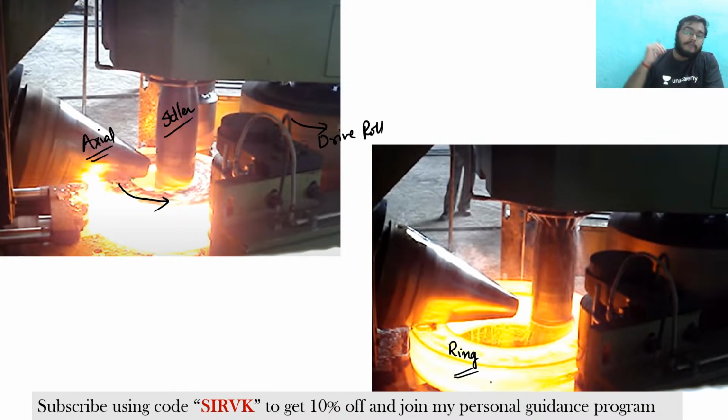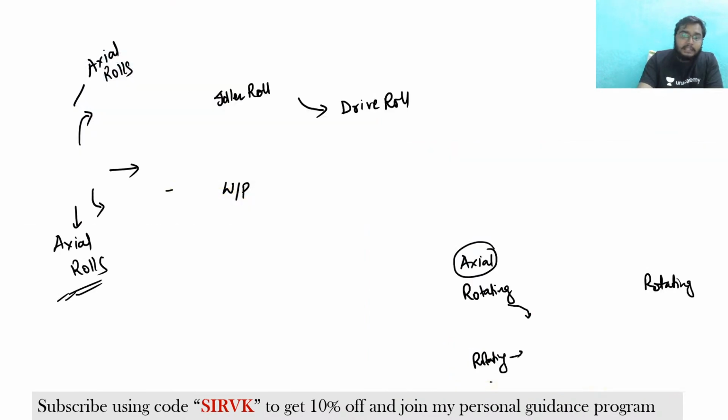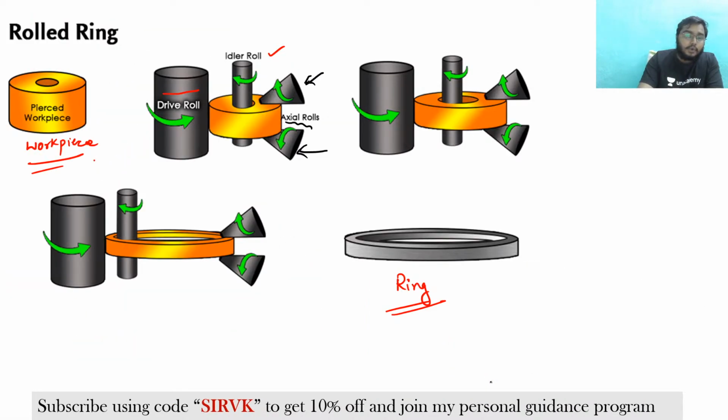So I hope you visualize these things, how in the industries, in the manufacturing unit, rings are produced with the help of rollers, and that's what is being shown in this figure. There is a workpiece, a drive roll, an idler roll, and axial rolls. Each and every fixture is rotating, and when it is rotating, a ring is produced. So this is the finished product.